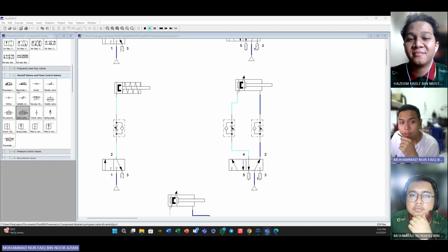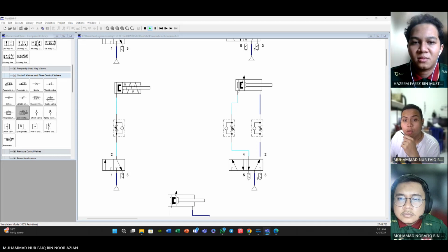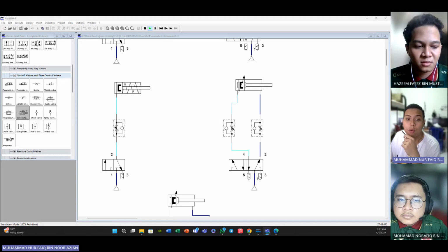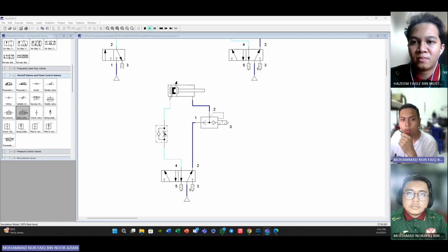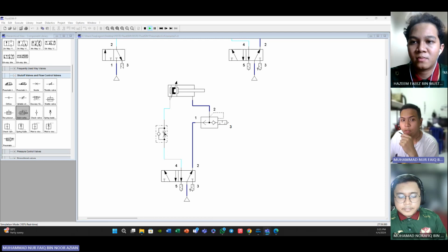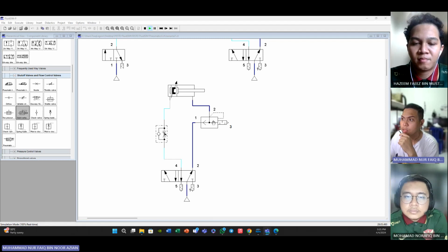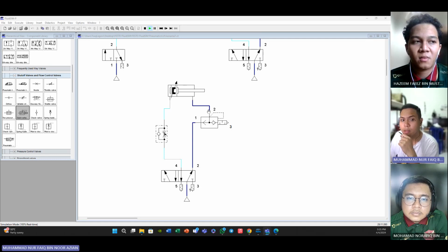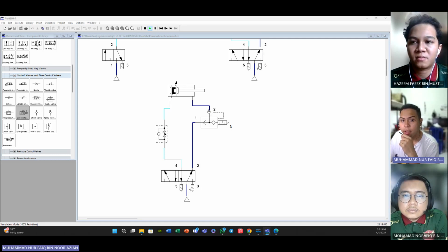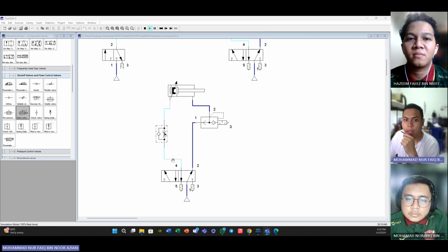Right. So if my memory serves me right, a pneumatic system compressed air line can be a few hundred meters long. So it will have a built-up pressure in the line that will slow the actuator to extend and retract. Alright, so I will show you guys. We countermeasure or solve it by using a quick exhaust valve to directly release the compressed air from the cylinder. So this is the quick exhaust valve, right? A quick exhaust valve will let the air out directly here at the cylinder. You see the exhaust here, port 3, and we don't have to go all the way back.